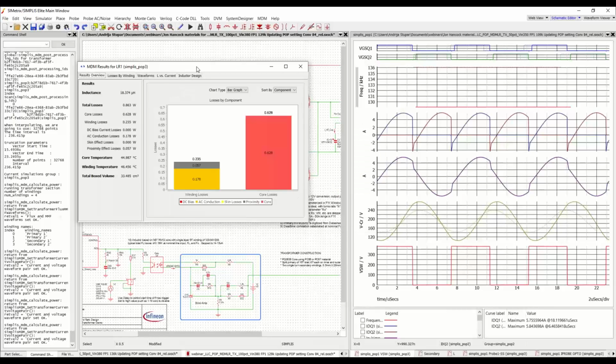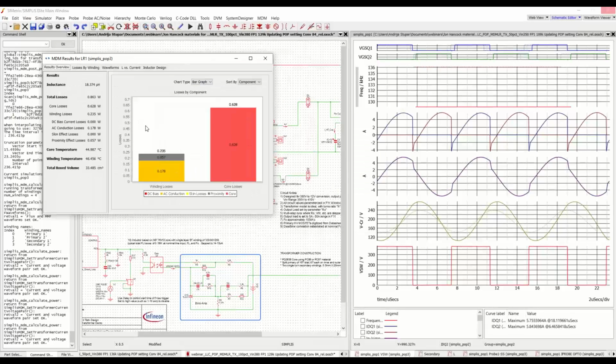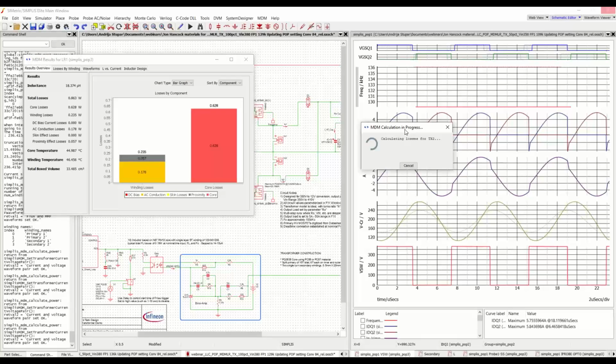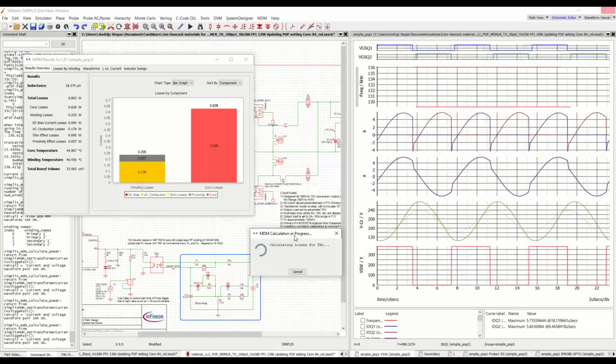So we can see that at full load, now our inductor loss has gone up to 0.86 watts. And again, as we're waiting for these transformer results, I can open the floor again for questions. We got one come in here. Does the core loss change the inductance value of the transformer?